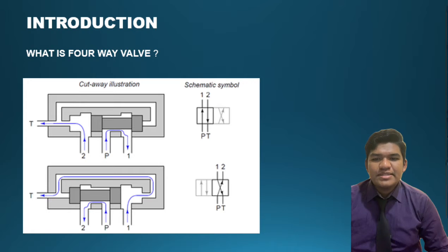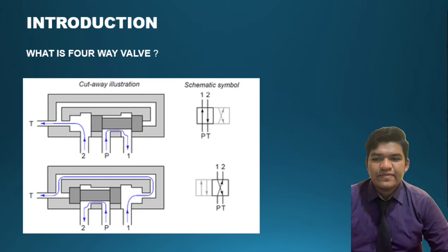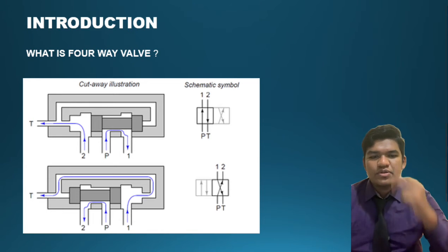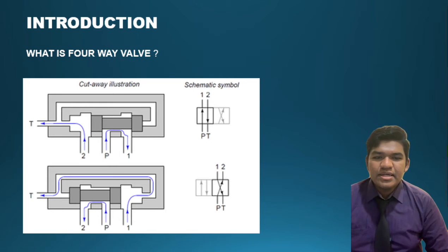A four-way valve uses a series of ports to control fluid flow in different directions using a single valve. The design can have a single inlet port with 3 outlet ports or 2 outlet ports to control flow from 2 direction sources. This valve can be operated manually or powered by air, hydraulic fluid or electricity.